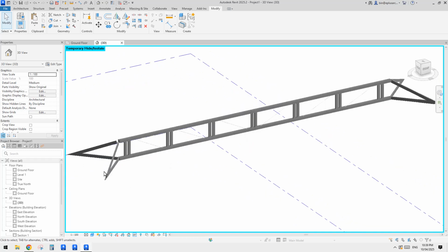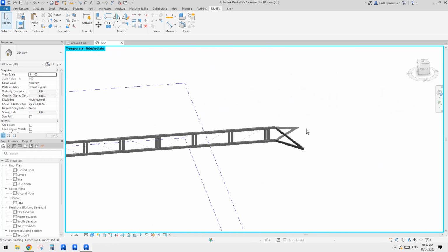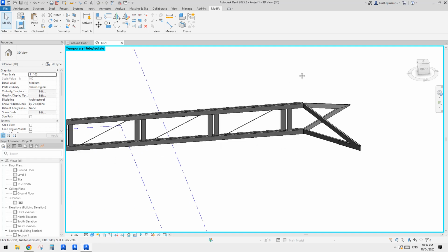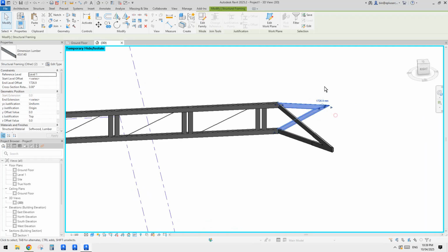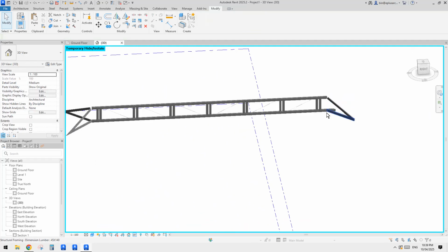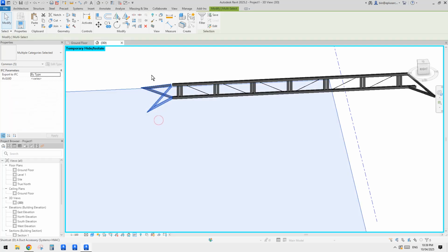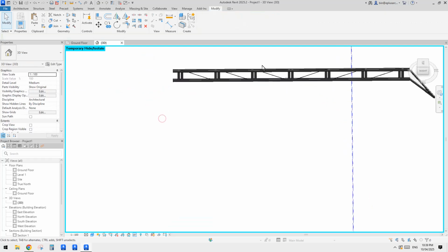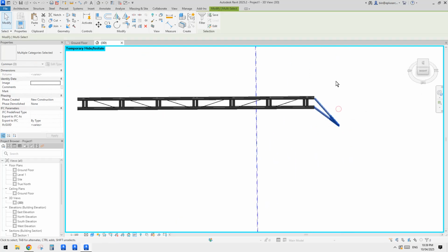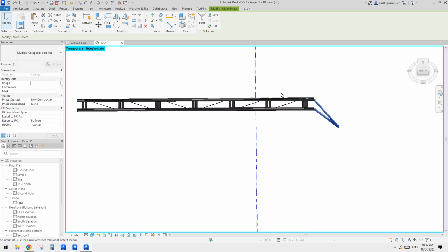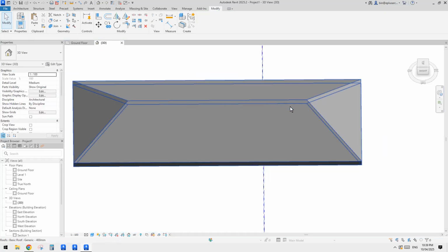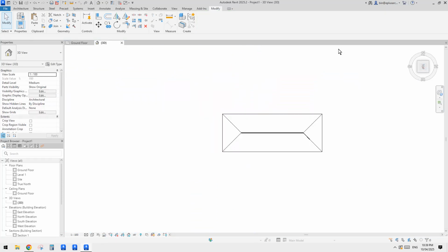Okay, so these are very ugly. I don't like them, so let's quickly fix them. Because it's all mirrored, we can probably just delete them. So we have this, right? I'll select this, and use HR to bring back the roof. Go to the top, WF.